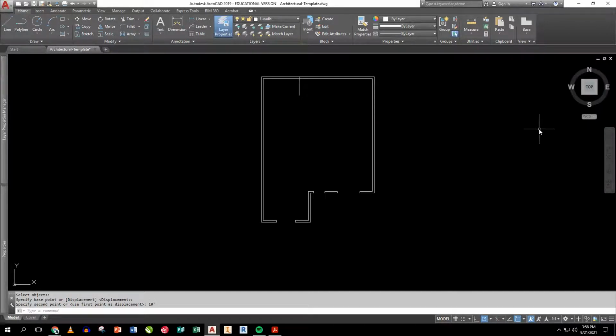Now, there's another window that is actually, well, let's do some math here. To the center of the wall, it's actually over 4 foot and 16 inches, which is 5'4". So I'm going to go offset, 5'4" enter. From here over.